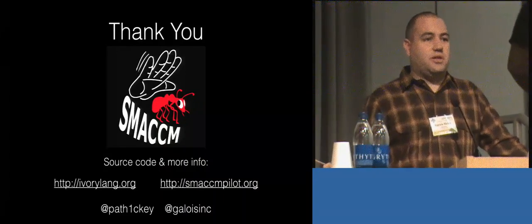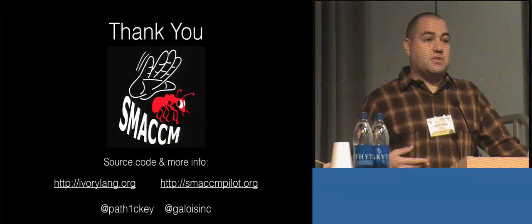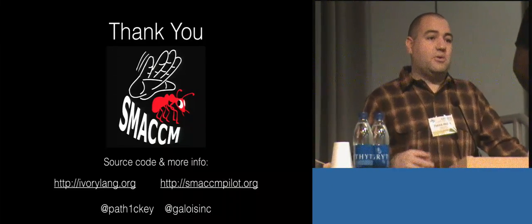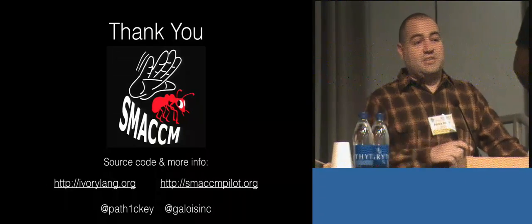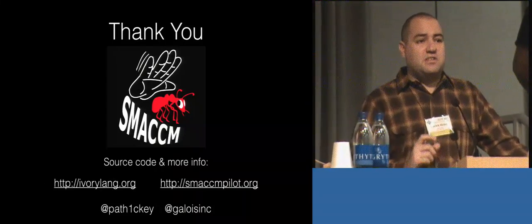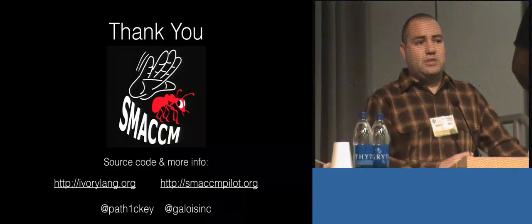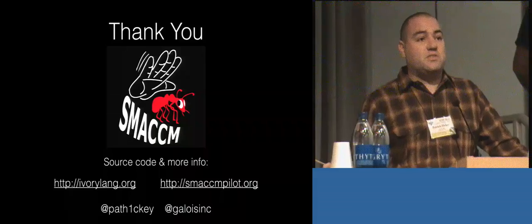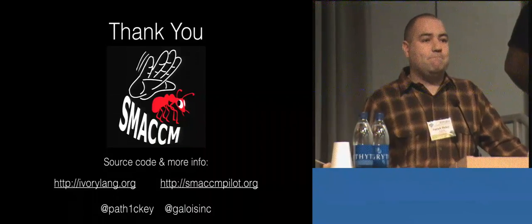That's something we hope to do in the future, using static analysis tools of the C program to be able to find out your maximum stack depth. Or you often have to use a static analysis of the machine code to figure out how the compiler laid out those stacks. So that's a difficult problem, and we haven't built up that tooling yet, but we think it's solvable. It's just that on a per architecture basis you would have to solve it.